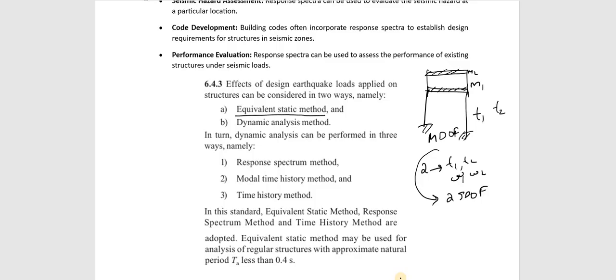But the responses from that method cannot be used directly due to the dynamic action. So we are mainly using dynamic analysis method. This method we normally do using some software. For example, we will be using software like ETABS, or we can use, you have studied about STAAD software, etc.